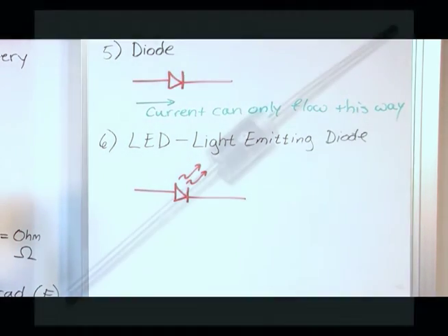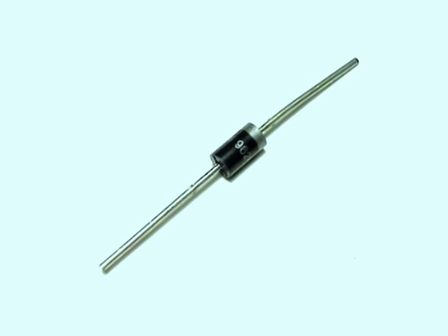All right? Okay, so here's a picture of a regular old diode. It's just a discrete component. It's about the size of a resistor, and notice that there's a band on one end. That band is telling you where that flat piece comes from that's on front of that triangle. That tells you that the electric current flow can go from this direction to the direction that has that band on there. That's telling you the orientation of the diode.